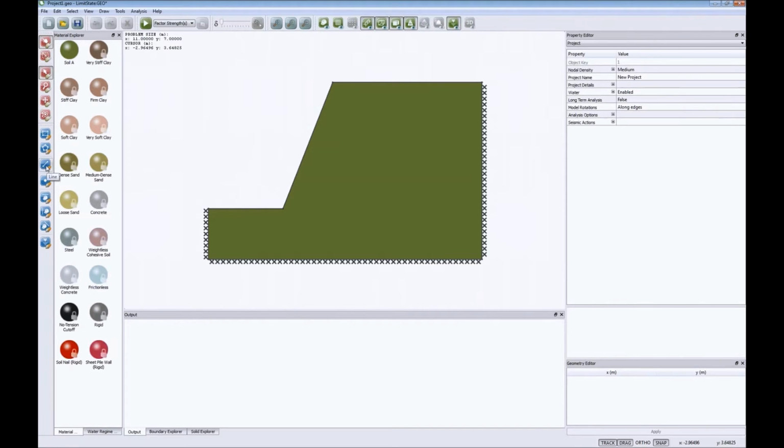engineered elements are modeled essentially on boundaries, which separate different bodies of soil. So the easiest way is to draw a line here, for example, and then up at a vertex at some point, and then if I want my reinforcement to act on that line, then I would apply it to that. So having selected that boundary, I can assign a property to it.